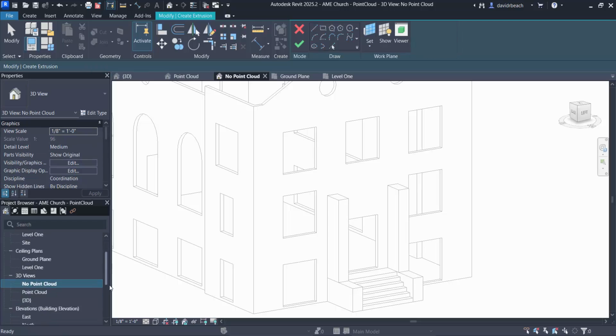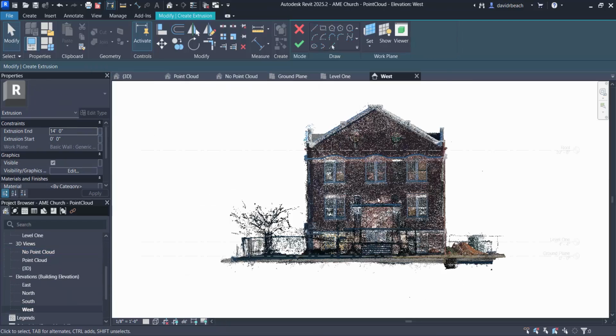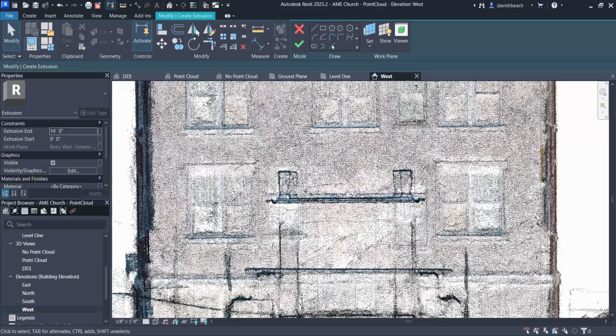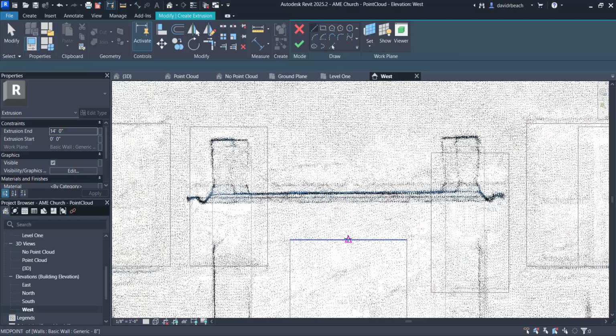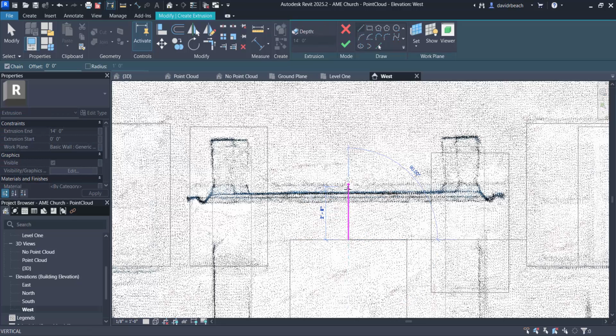From there, let's go to the west elevation, where we can see that roof piece right here. I'm going to set up that wall, so I'm drafting essentially on that west wall. So I'm going to go up to the top of that roof. It looks like it's 2 feet 6 above. I'm going to go over. It looks like this is stretching out right about 8 feet. And I've pre-measured the height of that as 1 foot 6 inches. So then this line comes across 16 feet.